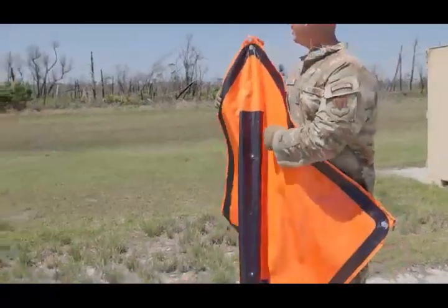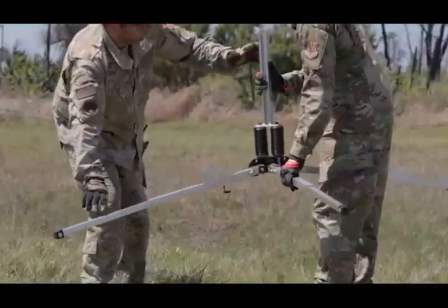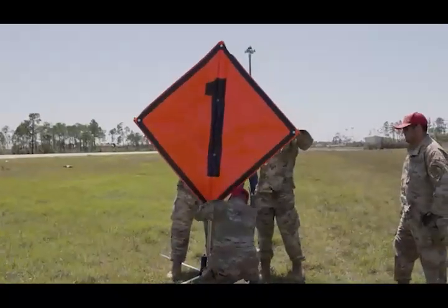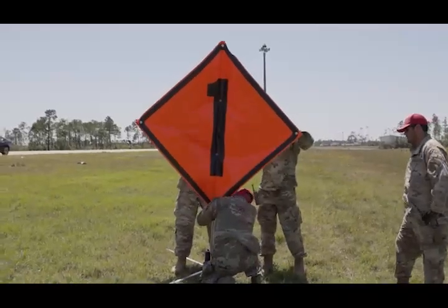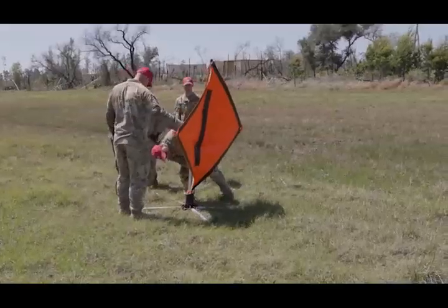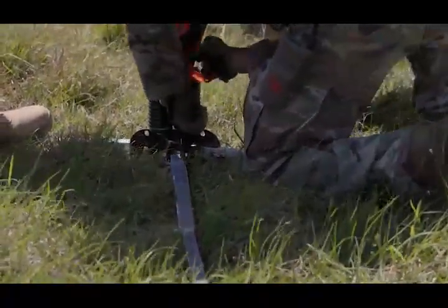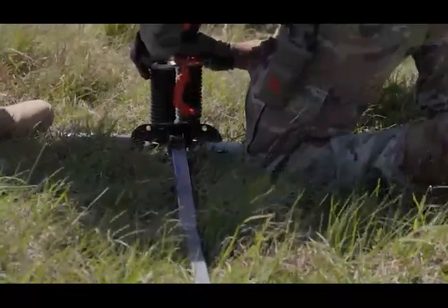Distance remaining markers are placed on the right side of the runway from the pilot's view, every 1,000 feet, starting 1,000 feet from the runway end. Place them 50 to 75 feet from the runway edge, or no more than half the runway width, and keep them away from PAPI units to reduce pilot confusion.